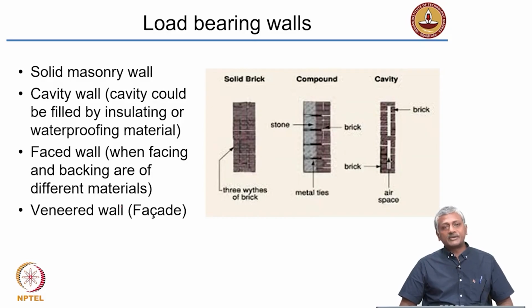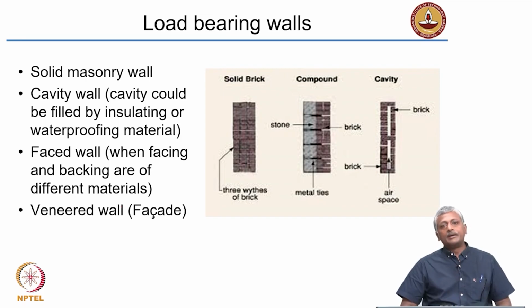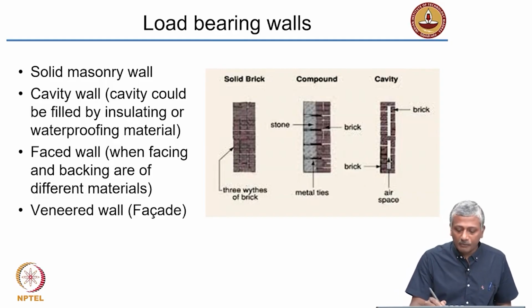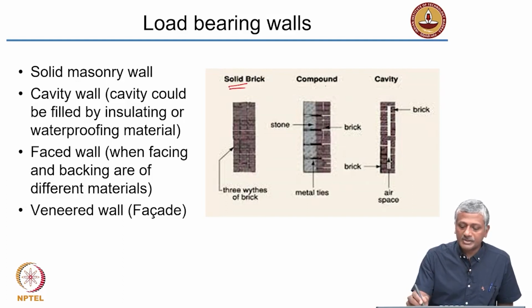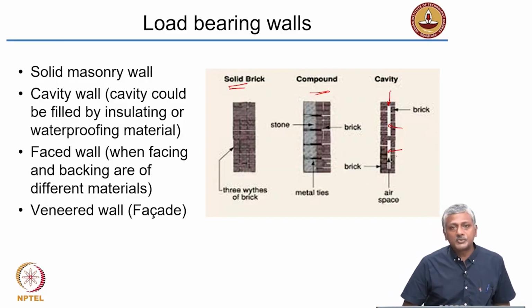Now, the load bearing walls themselves, as I said, they need to provide resistance to the load of the superstructure that is obviously there, and then transmit this load down to the foundation. At the same time, they should also ensure that the weather inside is nicely protected from the conditions outside. So, for that, we don't always use solid brick walls. We sometimes may use these compounded walls where brick and stone are together, okay. But more often than not, we'll use these cavity walls where the cavity or air gap inside will tend to reduce the transmission of sound and heat into the building, okay.